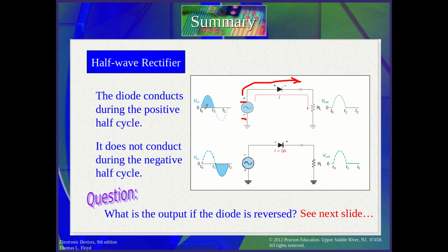So from T0 to T1, what's the behavior? As you see here, this is the input, V input. The diode conducts after 0.7, and the voltage will flow as normal, and we will see it at the output, V output, from T0 to T1. However, in the negative half cycle, the minus is here and the positive here, so the current will go this side this time.